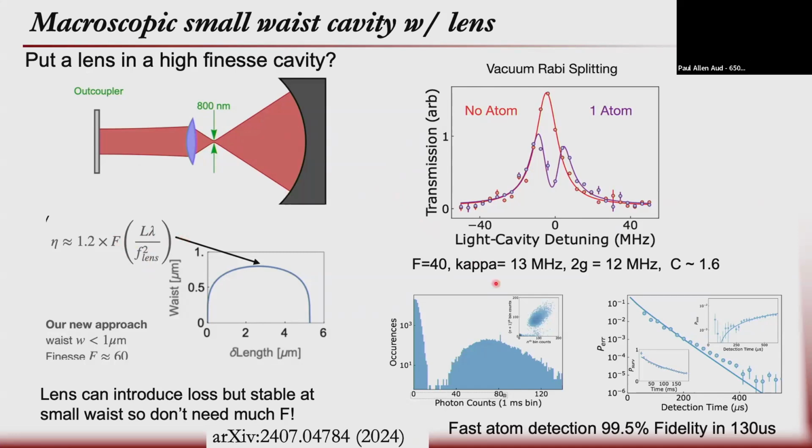And one application, with our stuff, you can use it to read out qubits. One of the things that's been limiting the neutral atom experiments is the readout time, which has been many milliseconds currently. And here, in this very first pass, we're already at like 100 microseconds. And you can see that this is 10 megahertz. So we should be able to get to better than a microsecond in principle. So that's a nice approach.